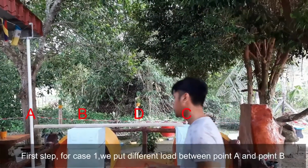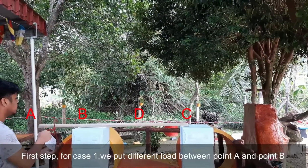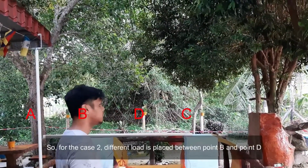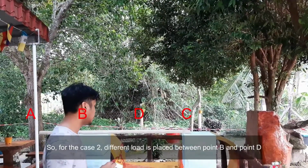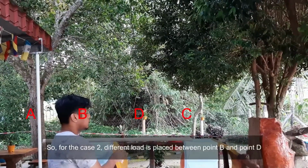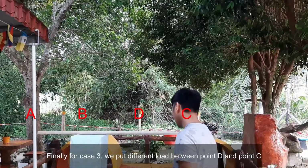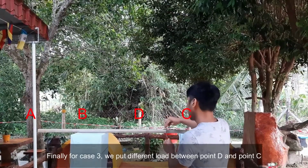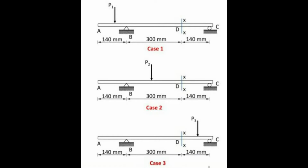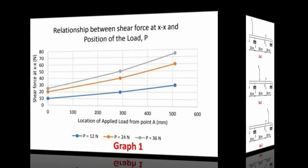For the first step, we put different loads between point A and B. So for case 2, different loads are placed between point B and D. And for case 3, we put different loads between point B and C. After that, measure the value of bending moment at section X for all three cases.